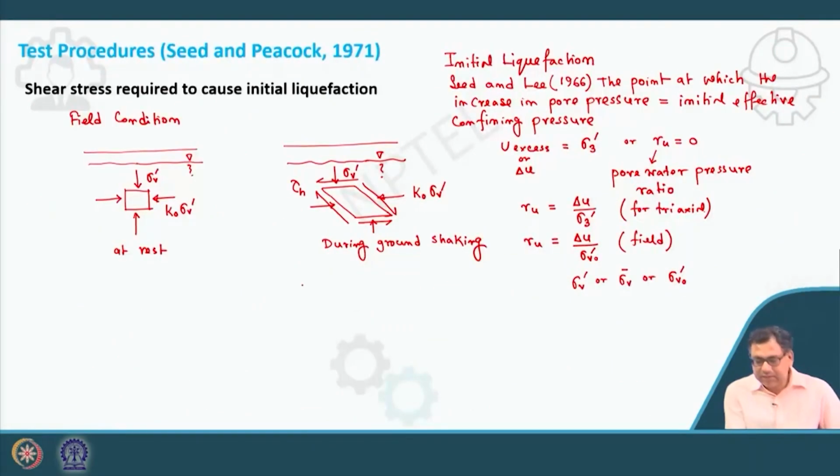Okay, cyclic simple shear stress, as I have mentioned in the previous class also, because in this test the field condition can be easily simulated as compared to the triaxial test. So, field condition I have discussed in my previous lecture. So, this is the field condition.